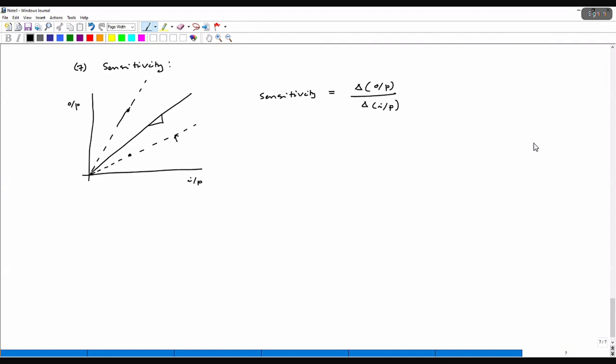Let's say this is the minimum sensitivity the data is giving. Let's say this variation is some delta. So, and let's say this is your Y nominal. Then you can define your sensitivity error as delta divided by Y nominal into 100.